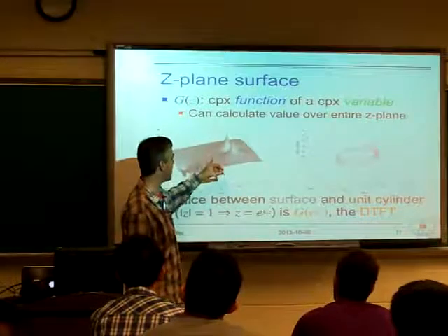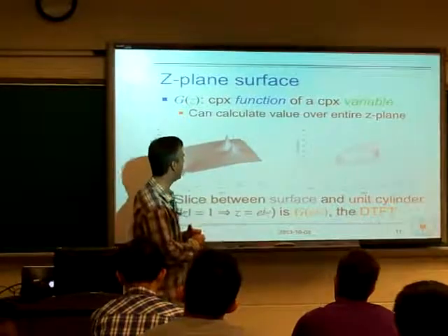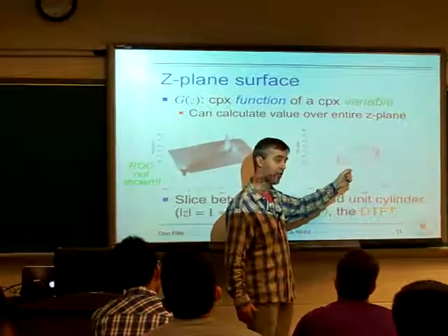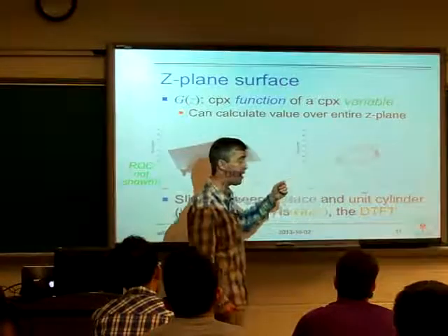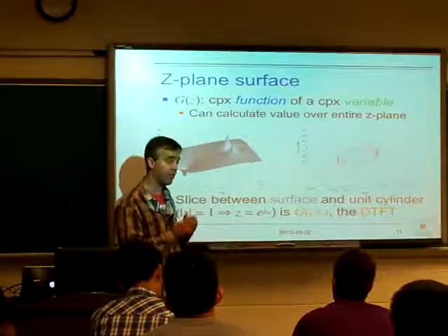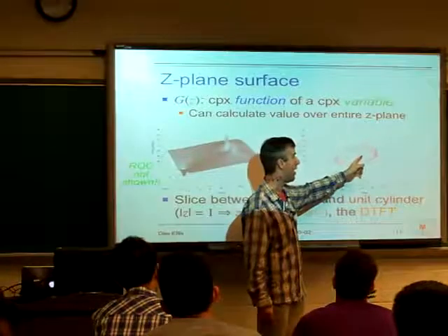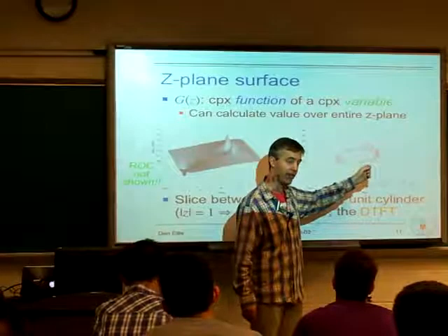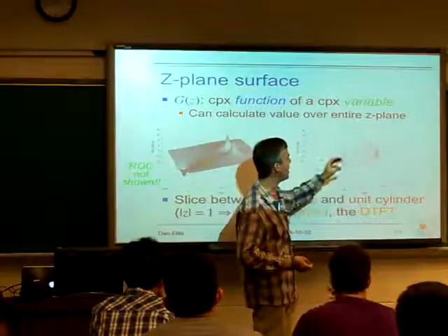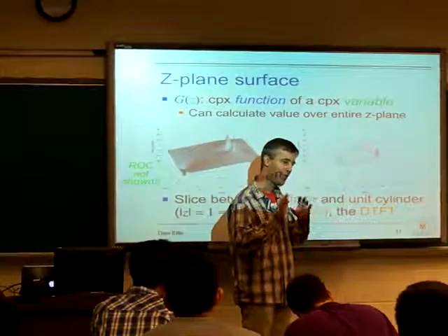But this was the Z transform of some sequence, and it had a region of convergence, which meant that it was the true values for some set of values of Z, and there were other values where it didn't work. Now, I started talking about the Fourier transform. It's like, oh, and that's the values of x of Z for Z of unit radius. The x of Z I'm talking about there is not the closed form expression. It's the actual Z transform, meaning I have to think about the region of convergence. And so here I want to take x of Z for Z equals e to the j omega. I want that to be the actual values of x of Z. This is only going to work if my unit circle is in my region of convergence, because otherwise when I actually evaluate x of Z, I just get these blown up values, right? So this relies on the idea that the unit circle is within the region of convergence. We'll talk about that more in a second, but thank you for pointing that out.